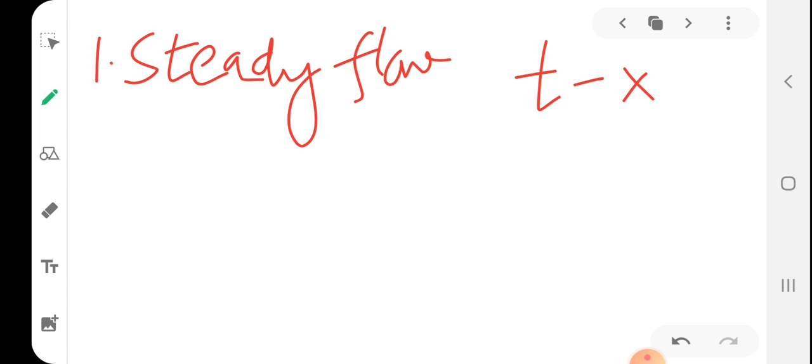In order to achieve a steady flow, the fluid particles must move along straight lines. Even though in real flow there may be turbulence which makes the flow somewhat unsteady, the solutions to these problems based on the steady flow approximation deviate only little from the real situation. So we can approximate this streamline flow as steady flow, so that we can avoid the presence of time as an independent variable. So we have removed time.